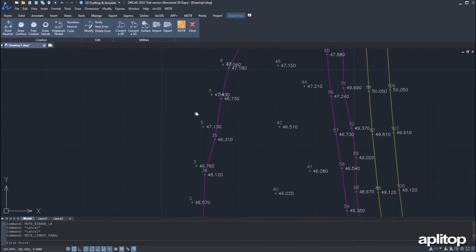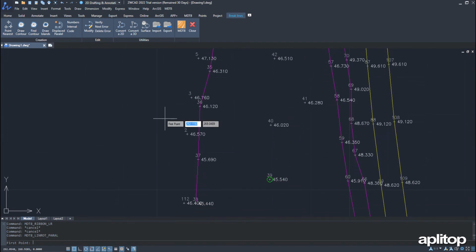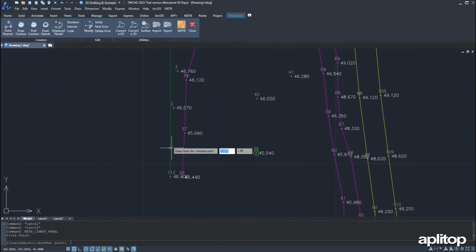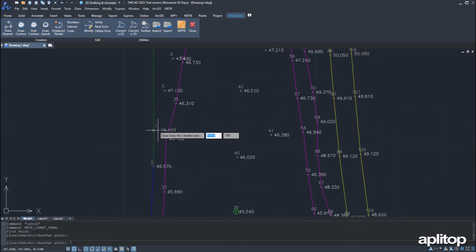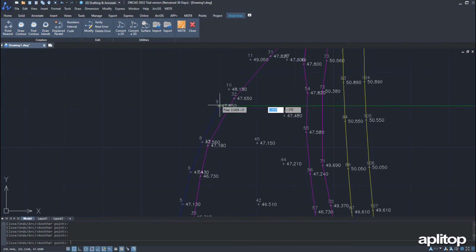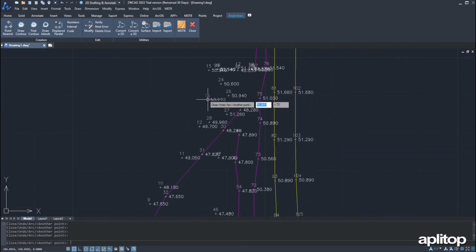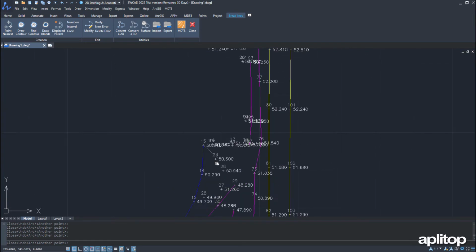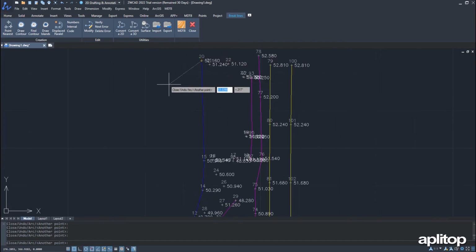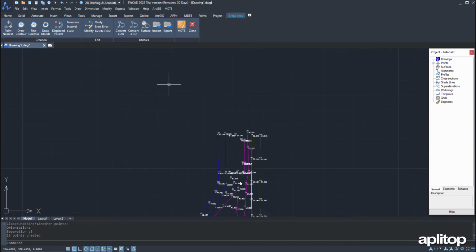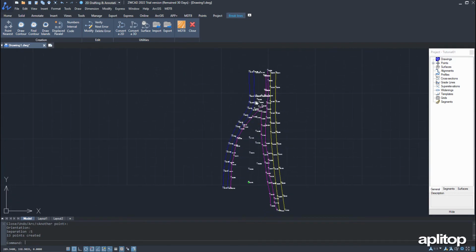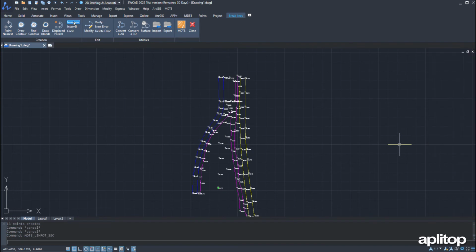We accept and graphically designate the points that define the path we have taken, in sequential order. We finish by pressing the right mouse button, and graphically choose the side to create the new points, and indicate the distance of the parallel line. We see that the points and the line on the other side of the road have been created.